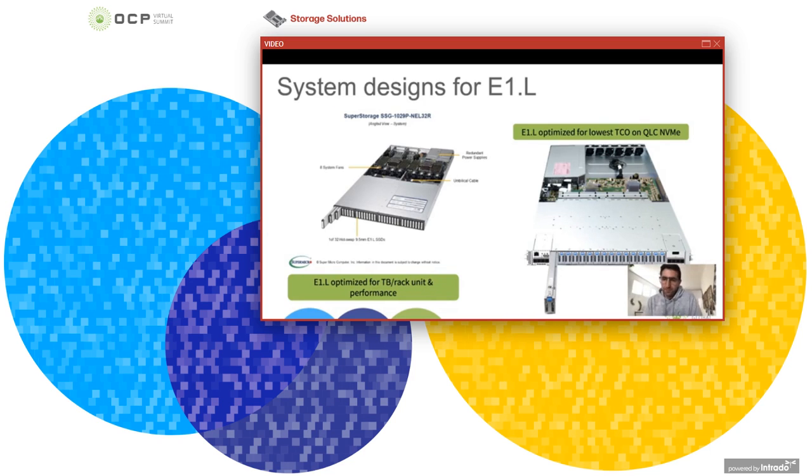So I'm going to talk a little bit about E1.L. I know I didn't talk too much about the spec because it hasn't changed as much, but I mentioned E1.L was really developed to be high capacity and low cost and best performance, for the best TCO. So one of the things that happens when you build a high capacity U.2 drive, sometimes some of the designs have two PCBs, and those PCBs fold over, and the components on the inside, like the NAND die and the SSD controller, get sandwiched inside of the drive.